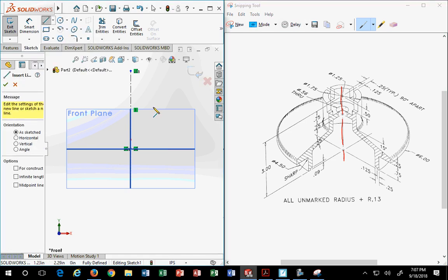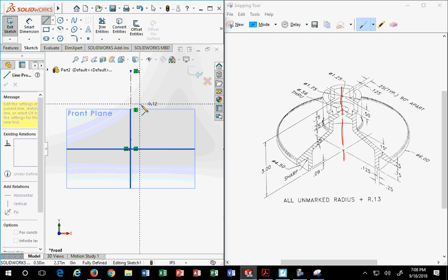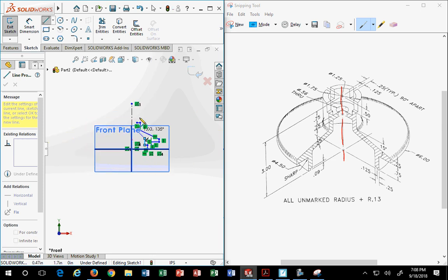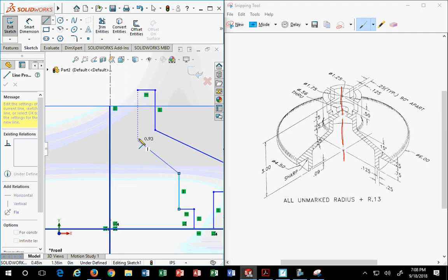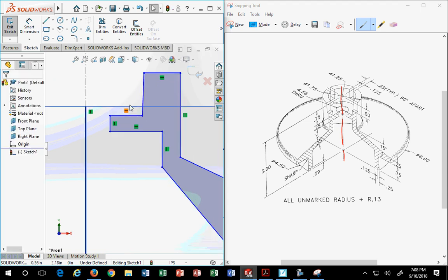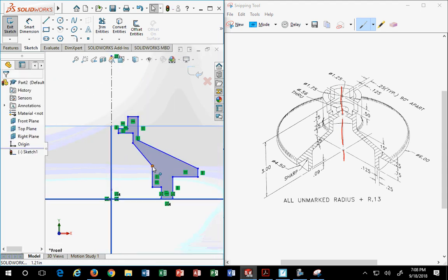If I now draw in some lines, let's say I draw a line there, there, off at an angle. I don't know, draw this line straight down, go down here, across, up. It is not dimensionally accurate if you haven't figured that out yet. I'm drawing a very, very rough drawing. Here, here. By the way, this is where the power of parametric comes in, because I can draw in such a haphazard manner, and then I can get serious about my dimensions